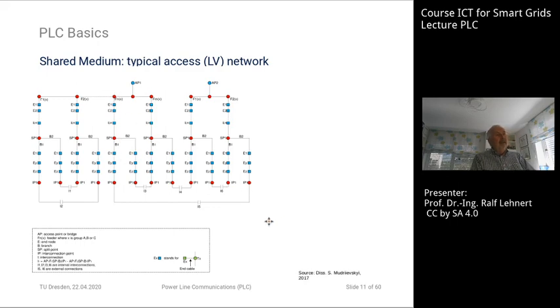So typically the low voltage network in city and suburban areas is a ring which is usually open, but in the case of failure it is closing or even closing automatically, so there is no outage if we have just one link failure.